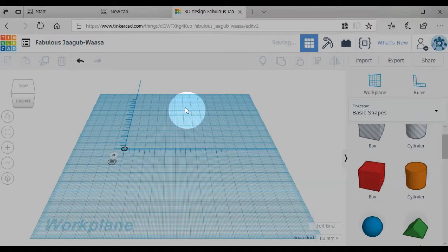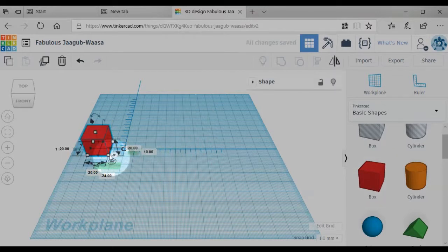A bookend has 2 basic parts: a horizontal base and a vertical brace that holds up the books. We are starting with the back of the base. For this, we go to the Basic Shapes palette and select a box. When the box is highlighted, there are square handles at the edges and corners closest to the build platform, and a 9th handle on the face farthest from the build platform.